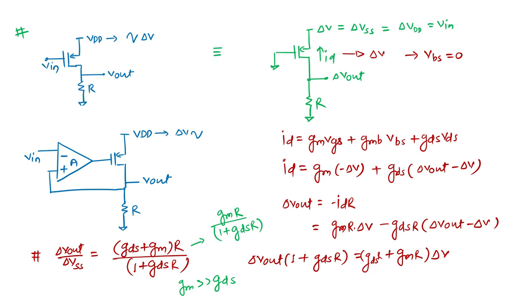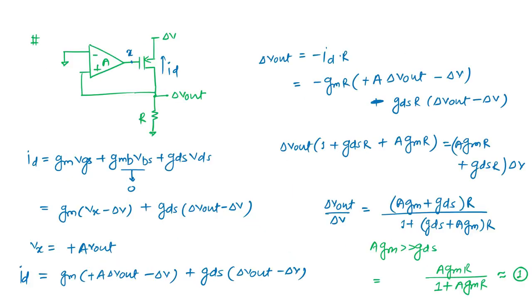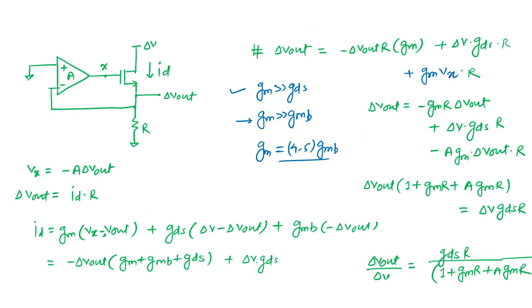Okay, so we must have good supply rejection, meaning that if there is some disturbance in the supply voltage, which is a very common fluctuation, we can go plus minus 1%, plus minus 5%, even plus minus 10% on the supply. In that case, our circuit should be robust to this disturbance, so that the output we get due to this disturbance is very small. We have seen this thoroughly in this discussion and also in the previous discussion for this particular circuit, where we had the common source structure.